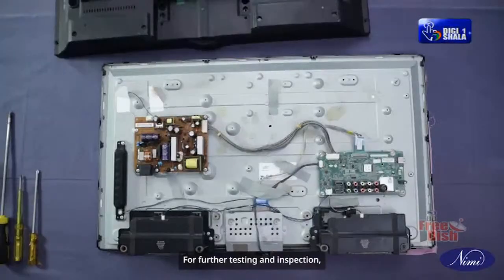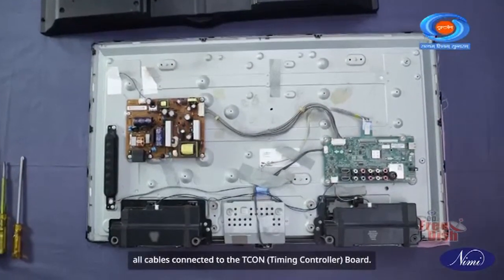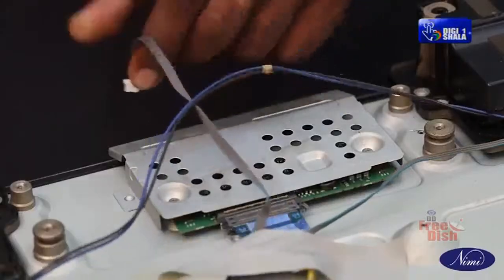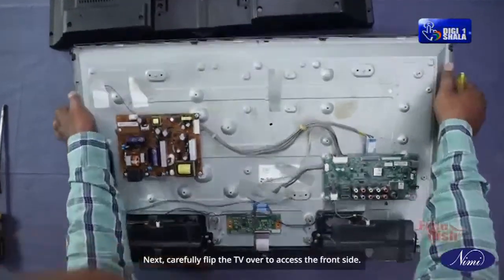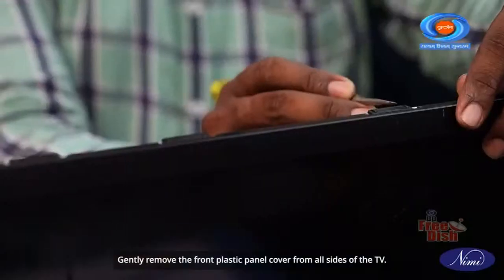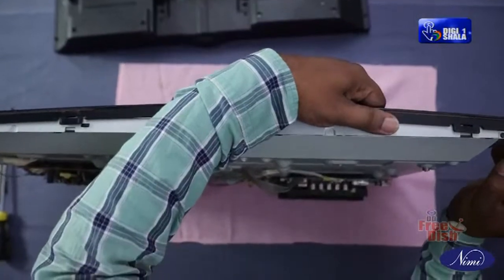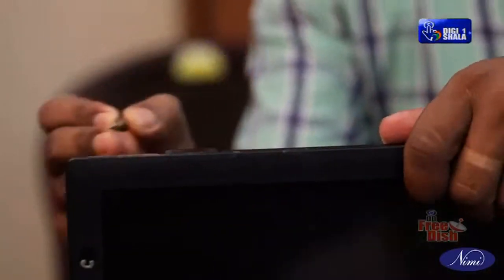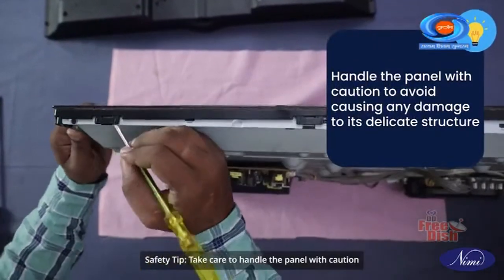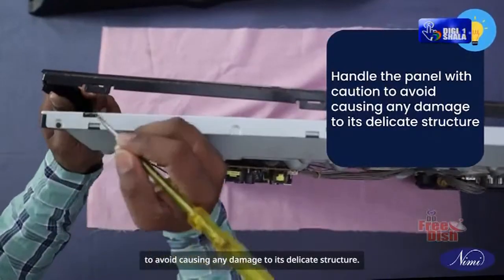For further testing and inspection, it is essential to begin by disconnecting all cables connected to the T-con or timing controller board. Next, carefully flip the TV over to access the front side. Gently remove the front plastic panel cover from all sides of the TV. Safety tip: take care to handle the panel with caution to avoid causing any damage to its delicate structure.